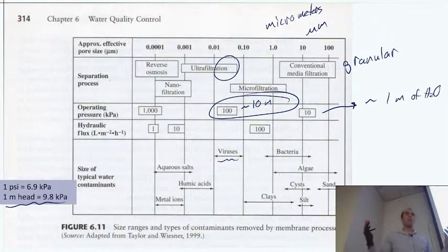So if we think about disaster relief or point of use filtration situations, if you can make a small water tower or store your water with some elevation, you could actually use the gravity feed there to power a membrane filter that can even remove viruses. So that can be a pretty good option. You just have to hit all that at the right spot and have some way of getting your water to elevation, which may require power. Okay, so a few tangible things like that for you.